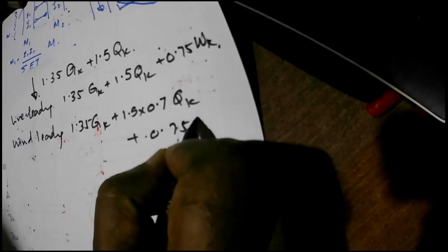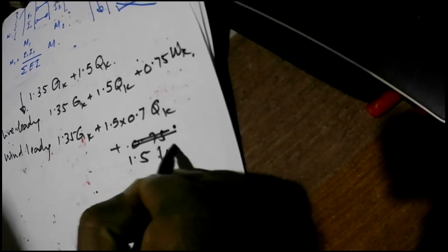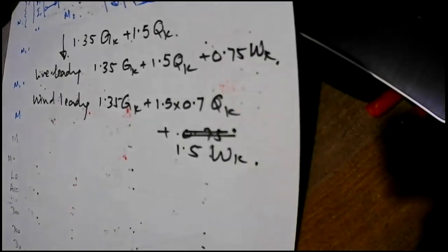And then we can also get wind leading case, 1.5 times WK, plus 1.5 into 0.7 times QK. So you can get this. And in addition to that, so this will give the maximum case.